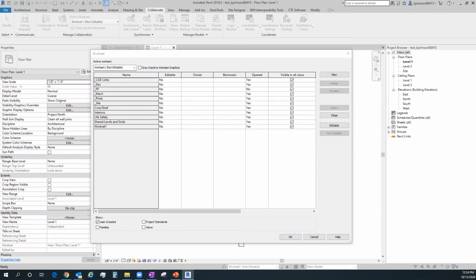Some people will say that you need to remove the backup folder and the actual file first. I could have Windows file manager open at that time and go into the correct folder for my save as. So I select that file and it's ready to hit the save button, but then I can go into my file explorer and delete my backup folder and my actual file. Go back into Revit, hit save, then it rewrites that file and makes the new backup folder, right? So then everything is rewritten.